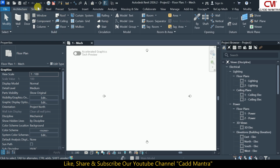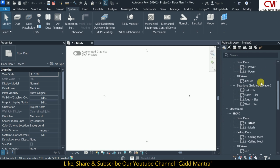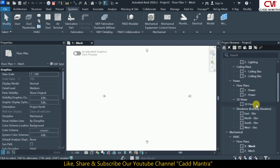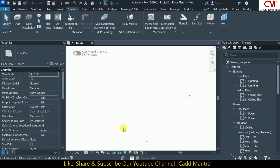Here are the different tabs. We will be working on systems, which contains all the mechanical, electrical and plumbing parts of the software. Over here is the quick access toolbar. Here are the properties. On the right side there is the project browser, which contains all the plans, ceiling plans, elevations, etc. In the middle, we have the workspace in which we will be creating our models.